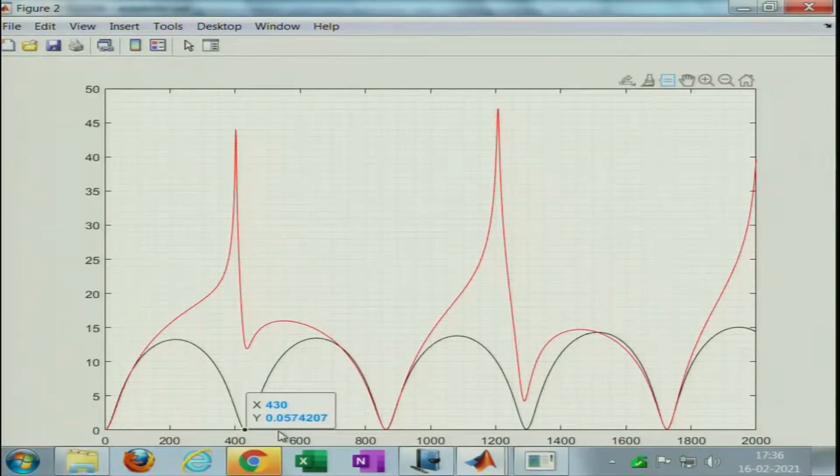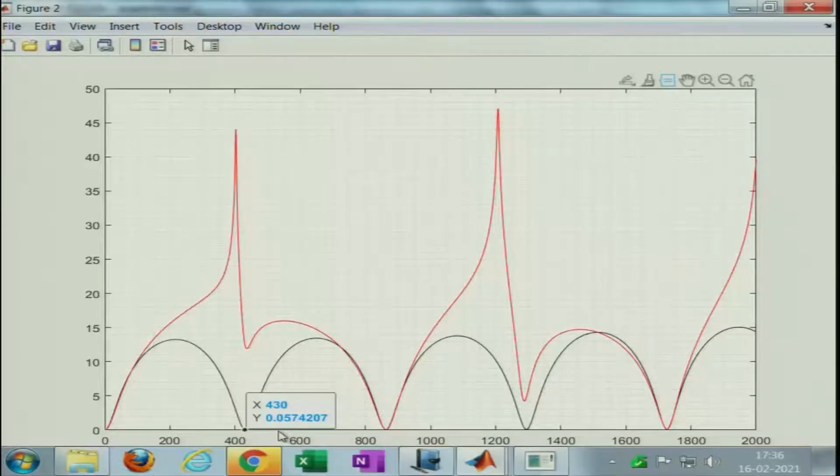Now, remember for a concentric chamber with extensions at the inlet and outlet, if we just had a tube with L by 2 length, theoretically it would have exactly tuned the performance. We saw that. But then, it does not really happen because of end correction effects. There were some end corrections. You would also have done some assignments related to that in the last couple of weeks or so. But here we are deliberately choosing L by 2 and assuming only plane waves, and still theoretically able to tune the performance. Okay. And that is really because of the perforate impedance.